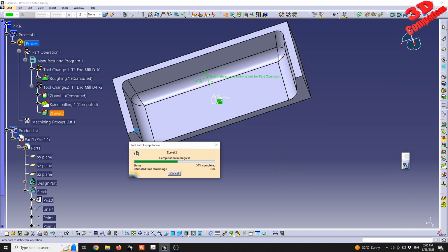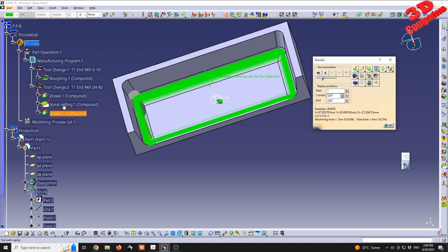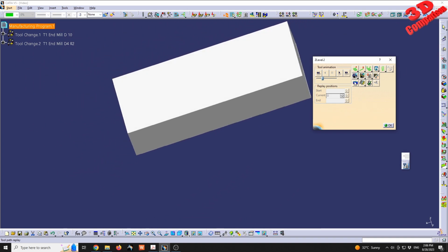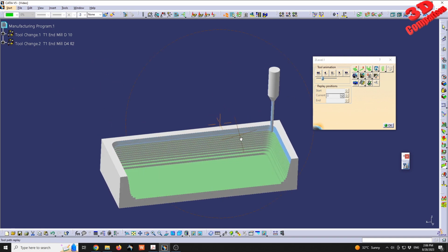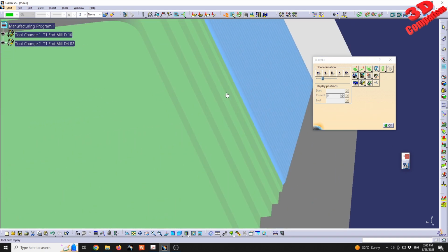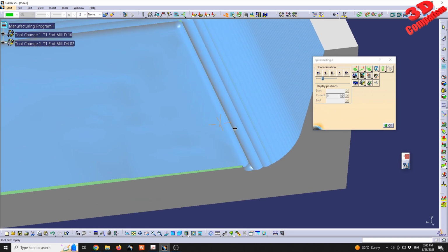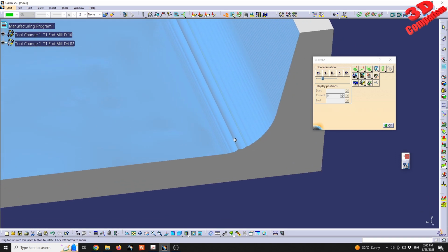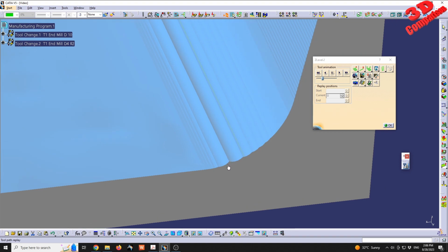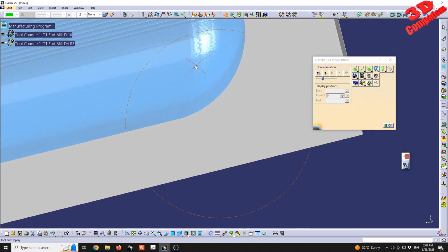So for this case study, there are quite a lot of finishing operations, so usually you won't use so many. But I wanted to present various changes that you can do within the machining options to see how that final surface will look. And we see those operations, and now we should have that finishing operation that should slightly adjust those slopes. We are still within the ZLevel, end of simulation.